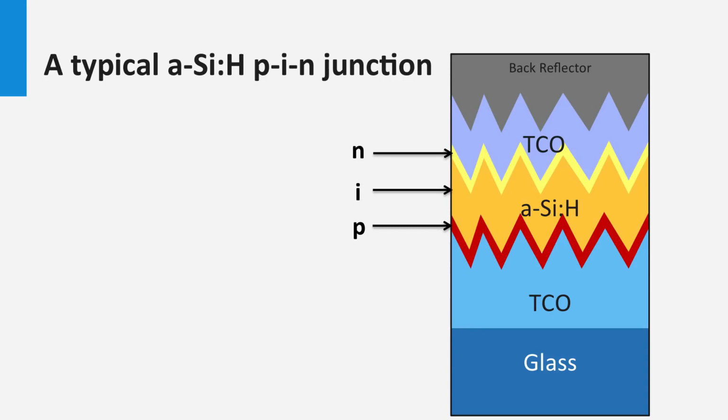P-doped layers are boron-doped amorphous silicon, but also higher bandgap materials such as boron-doped silicon carbide and silicon oxide layers are used to enhance the transmission of the bluish light into the absorber layer. As back reflector, usually a TCO and metal back reflector is integrated into the device. Metals are either aluminum or the more expensive silver, which has a higher back reflection compared to aluminum.